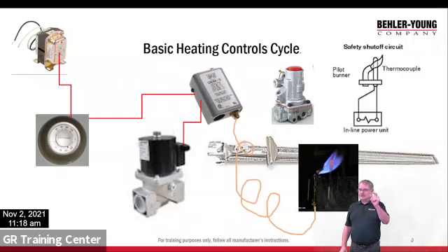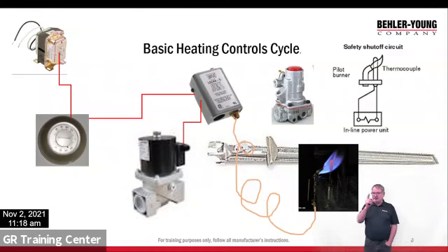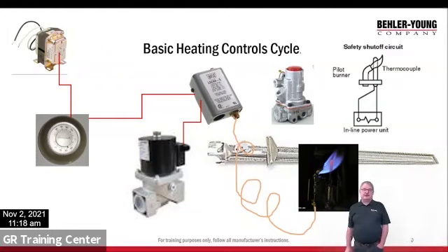So remember that electric magnet we made with the nail? Well, I'm going to do the same thing, but I'm going to use voltage that's being generated from that thermocouple. So you heat it, it creates a very low millivolt. I feed that to the pilot safety, which is one of the two up there. So if the pilot goes out, the safety opens and it doesn't allow the main valve to come in. All right, so it's pretty simple. It's really pretty ingenious. You think about this stuff was created 100 years ago.